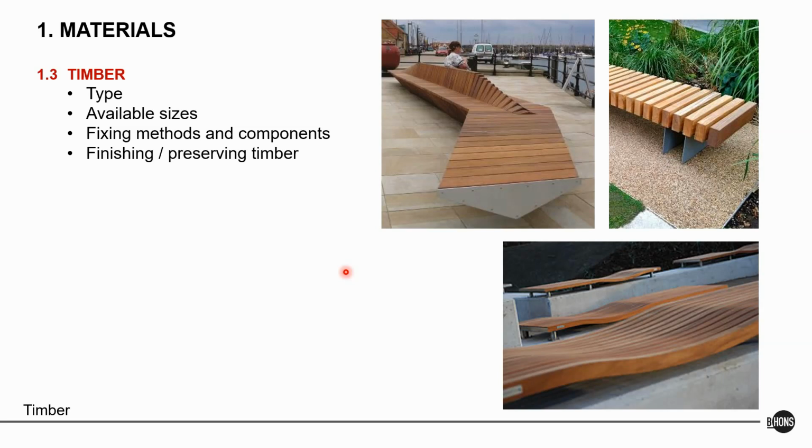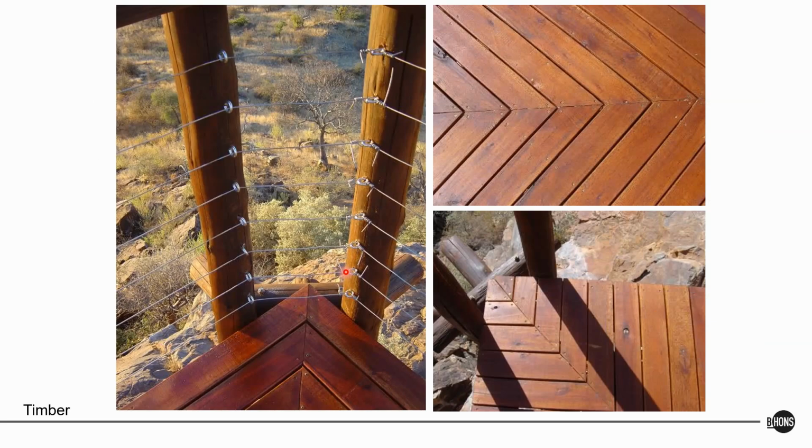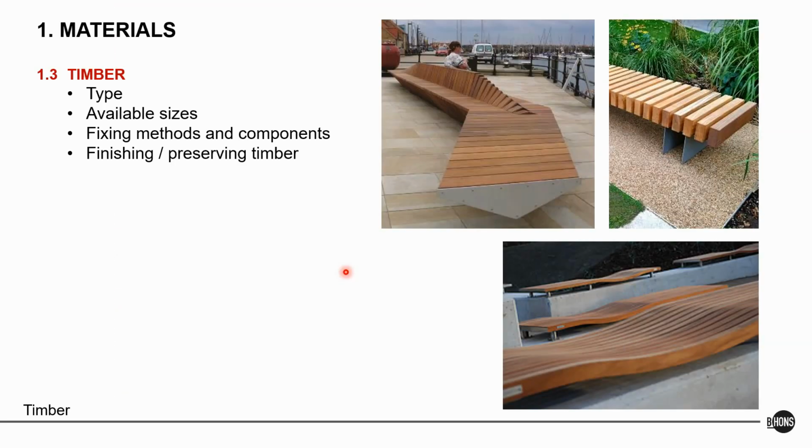It's like varnish, really, on top of it, and those have to be fixed and preserved quite often. So every few years you need to sand it off a bit and then paint it again to keep it. So think about where you install the timber and how you can actually access it later, to ensure that it is still useful after a number of years, because that's one of the major implications of using timber.